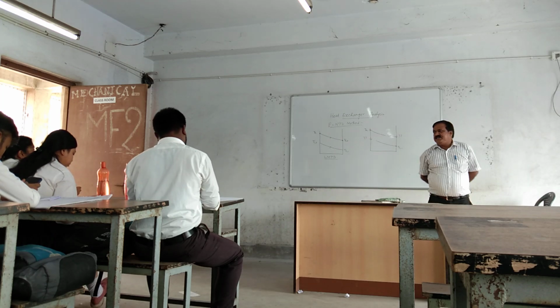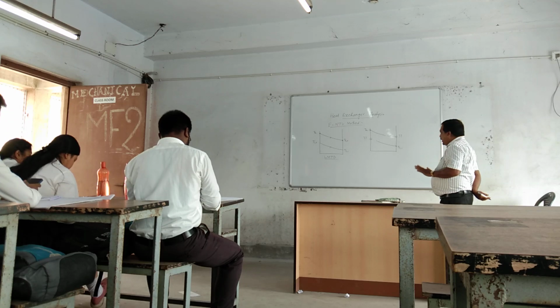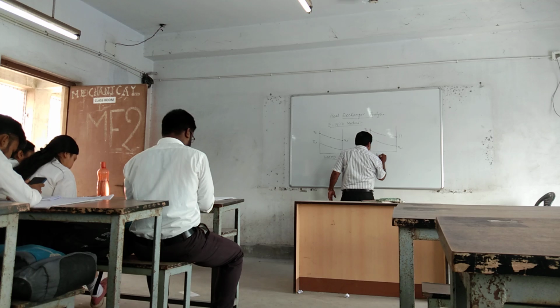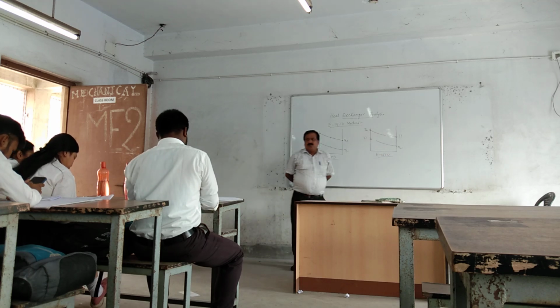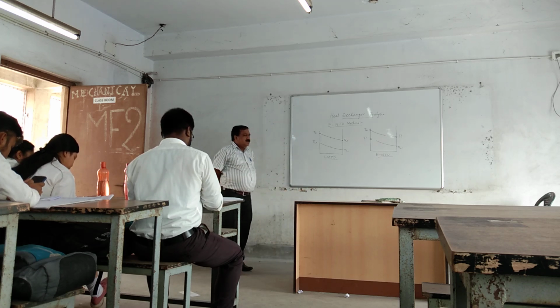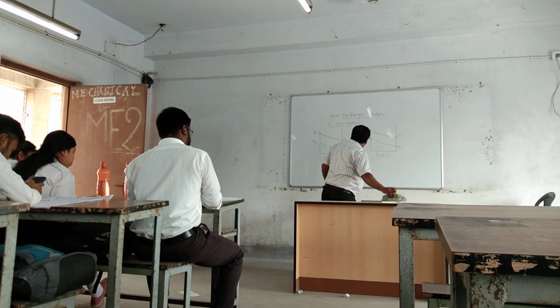Only the inlet temperatures are known to us. When all the temperatures are known, that was for LMTD analysis. In this case, we shall do it by the epsilon-NTU method, when only the inlet temperatures are known.